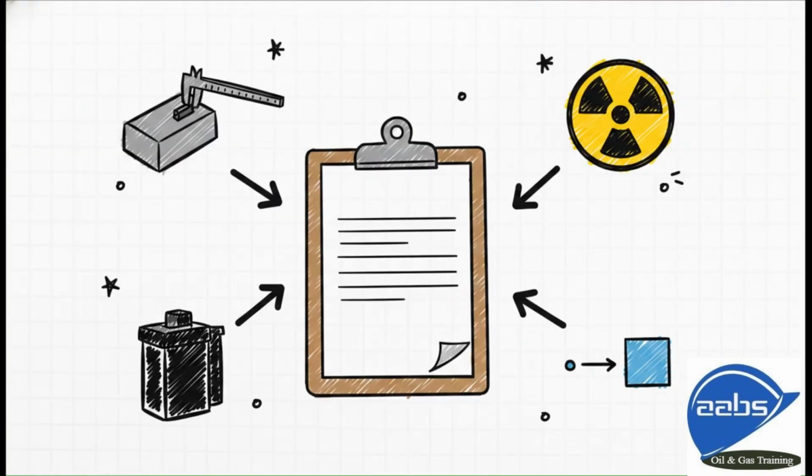So, here are the absolute non-negotiables for your setup. The ASME code requires you to strictly follow a written procedure detailing these exact parameters. You simply cannot wing it. You have to document the exact material type and thickness, whether you're using an isotope or an X-ray machine, the precise source-to-object distances, the specific film brand, and the exact screens used. If these aren't locked in from the start, any interpretation you make later is legally invalid.